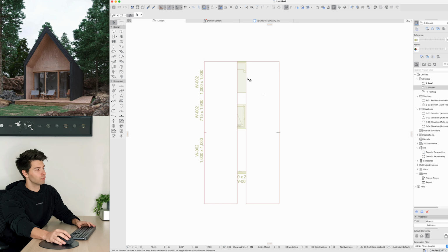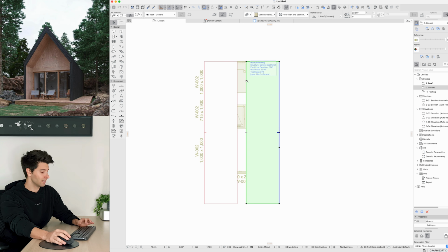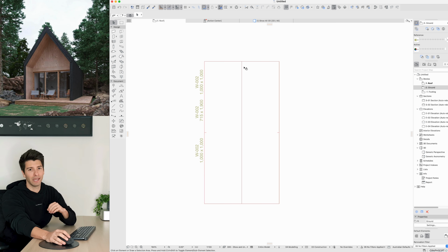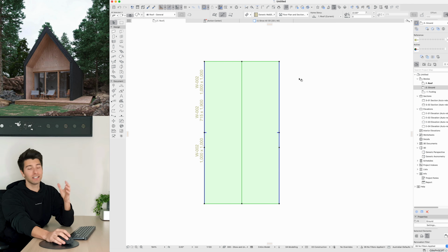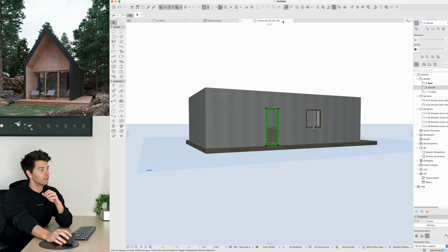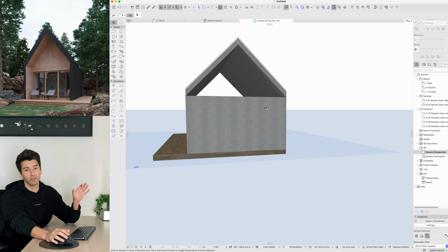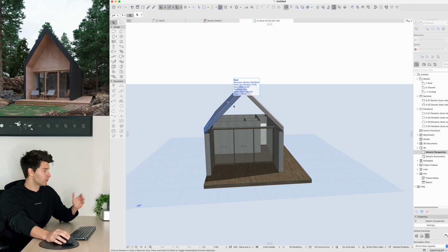And then to connect these roofs perfectly in the middle, let's select one, hold Command, click on one edge, and repeat the same step to have those roof panes automatically join. Now, if I select both of these roof panes, we're going to see that it's 22 degrees. That is a very low pitch for what I'm seeing here. So I'm simply going to type in 45 degrees, go to 3D, and we are going to see we've very quickly created our roof.